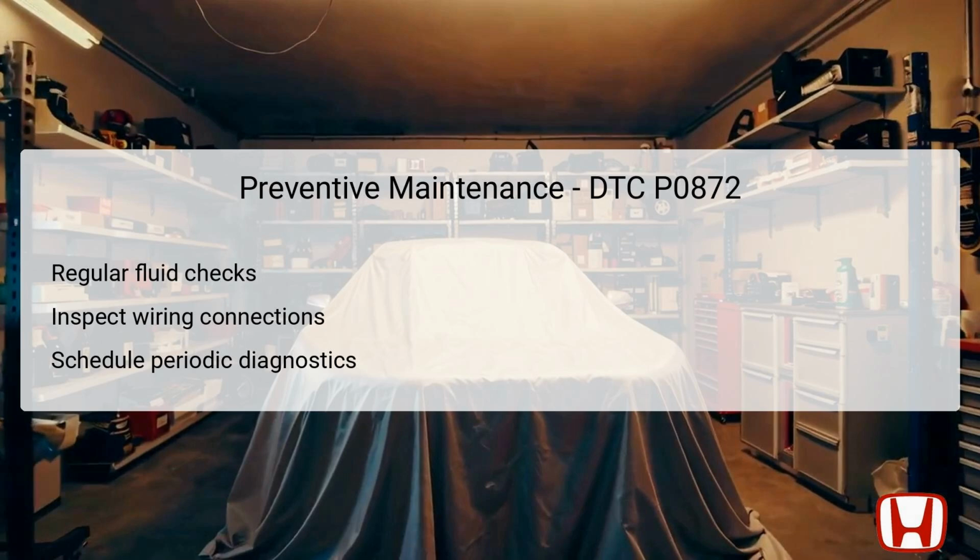Additionally, inspect all wiring connections associated with the transmission fluid pressure switch regularly to prevent shorts or corrosion, which can lead to erroneous signals. Scheduling periodic diagnostics using the Honda Diagnostic System can help in early detection of malfunctions, allowing for timely interventions and repairs. This proactive approach ensures that the vehicle maintains its transmission integrity and enhances overall driving comfort and safety.